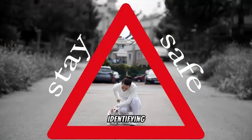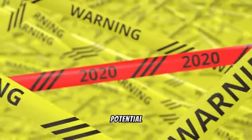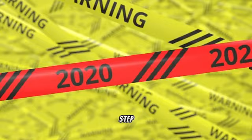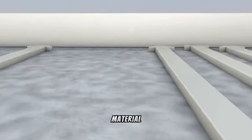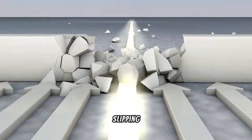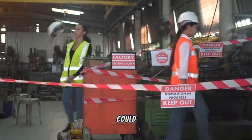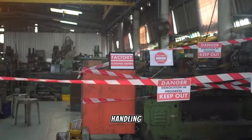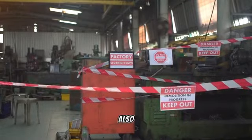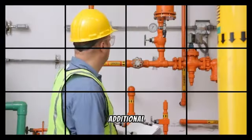Next step is identifying the hazards. So after you've gone through the task and the tools and the workplace layout, then you need to identify the potential hazards associated with each step. So for the task of feeding material into the machine, some of the common hazards could be the material falling or slipping, which could cause an injury; entanglement with moving parts of the machine, which again could lead to an injury; and improper handling of the material or tools, which could also lead to an injury. So those are some of the common hazards. Of course, depending on the industry and the workplace, there might be additional hazards.